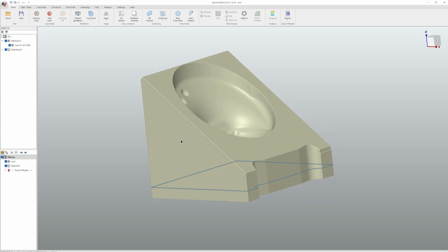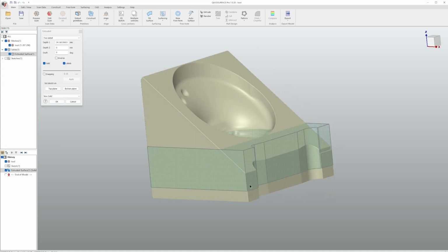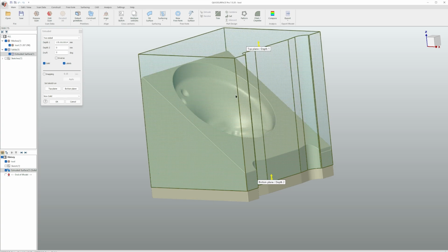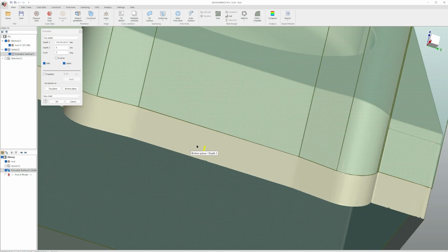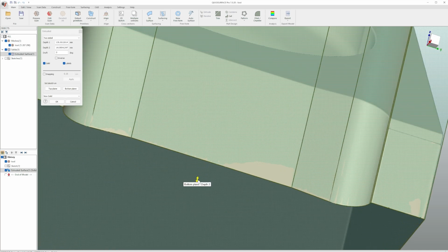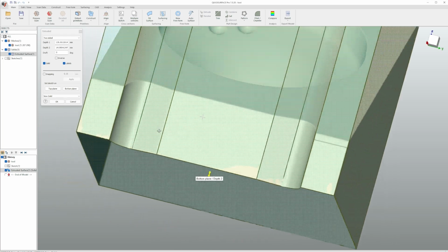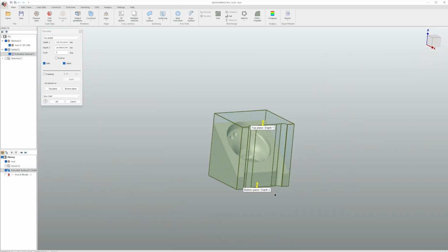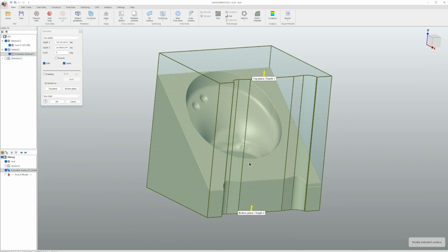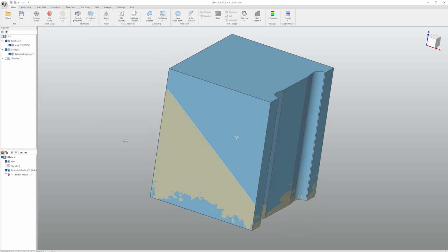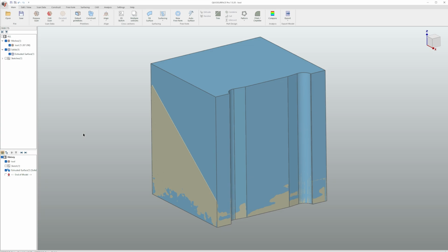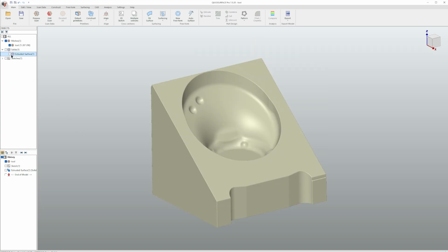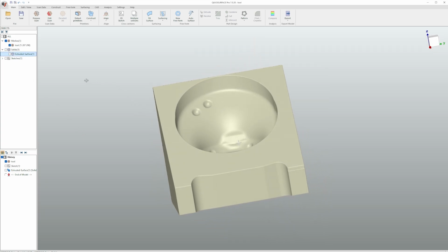From this stage, click on your sketch and click the extrude button. With the top arrow, simply extrude it past the mesh, and with the bottom arrow, move it down until it reaches the bottom of your mesh. With this done, you can click OK. For the next step, hide your main body so we can continue with the auto surface part.